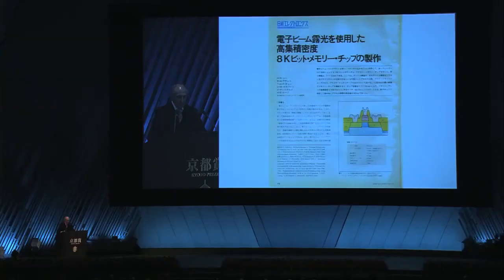Even for the small arrays which were appropriate to the design and ground rules of those days, the number of terminals which could be assigned to bit lines represented a big limitation to that. We knew that on-chip sensing circuits were desirable, but there was very little experience with MOS circuits for sensing small voltages. The variation in the threshold voltage, the gate voltage required for turn-on, was quite large in those days.